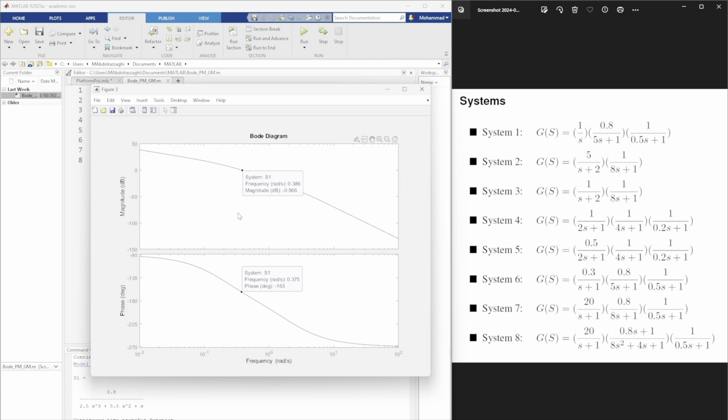But on the other hand, one might ask what would be a practically decent level of gain margin and phase margin? Essentially, a good region for the gain margin is something above 6 dB. That's called a good region for a gain margin. In our case, that's 9 dB. And a good region for phase margin is around 40 degrees, in most of the practical cases. In this case, we don't have that good a phase margin, by the way, only 17 degrees.